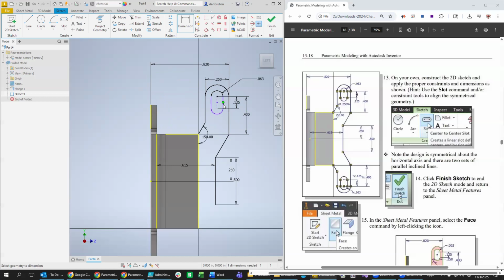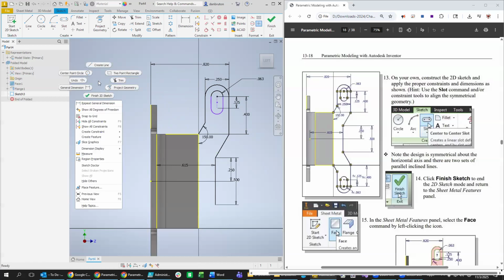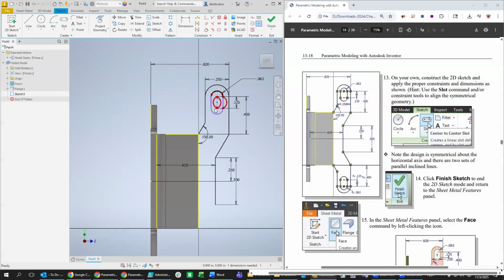So is it the fact that it's not vertical? So we'll get confused about that. We just do this right here, and it looks like it could actually rotate, which I don't know how it thought that that was the case. But when that happens, we look along the y-axis and say that's vertical, and then try to make this vertical as well. And it did that. Fully constrained now.